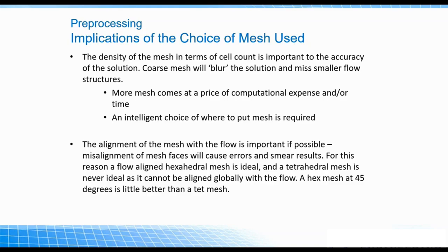So to start, an important point is that your mesh is important. If you have a bad mesh, you will most certainly end up with a bad solution. If your mesh is too coarse, especially in areas of a high gradient solution, you're probably going to miss some of the solution there and come up with the wrong answer. If you have too fine a mesh, on the other hand, you will end up wasting computer resources and a whole lot of time solving for a finer mesh than you really need to. So ideally, we can be as efficient about this as possible.